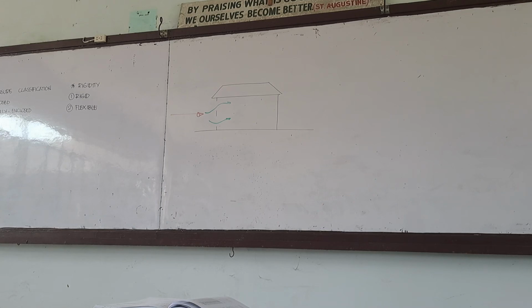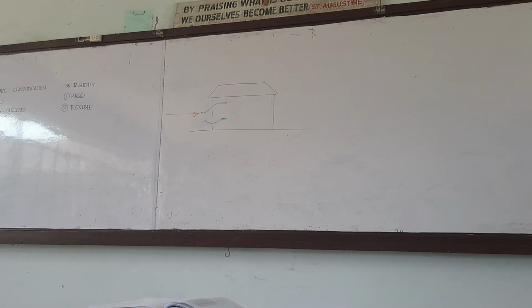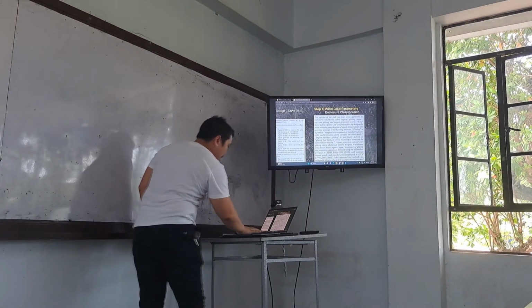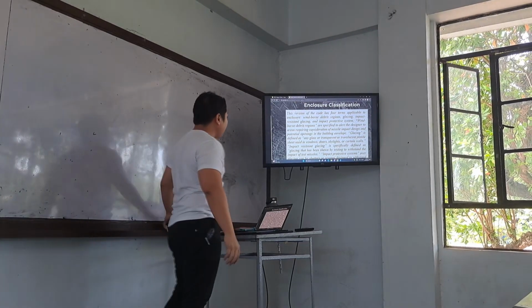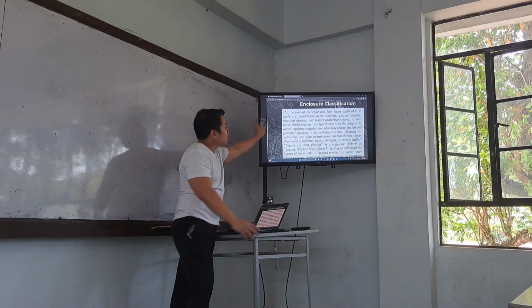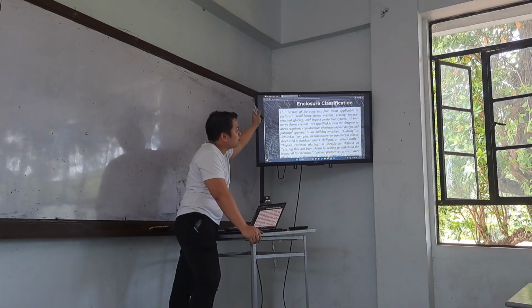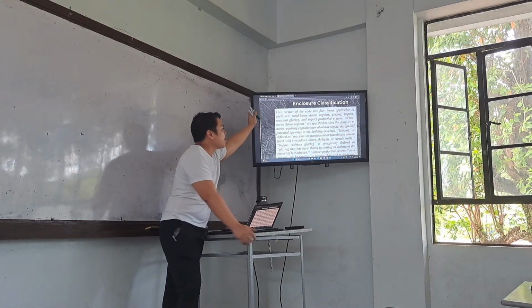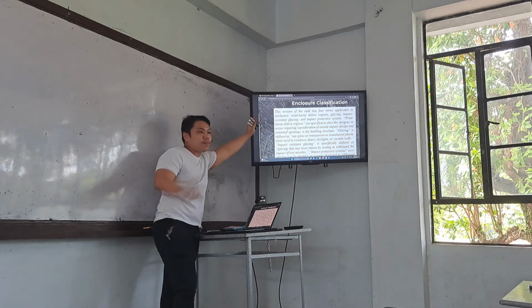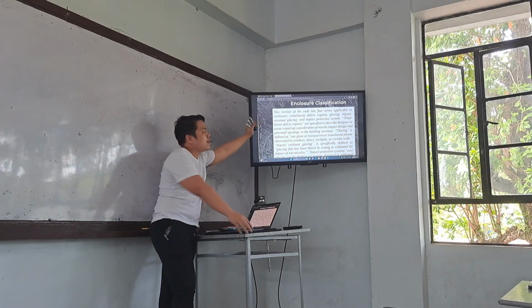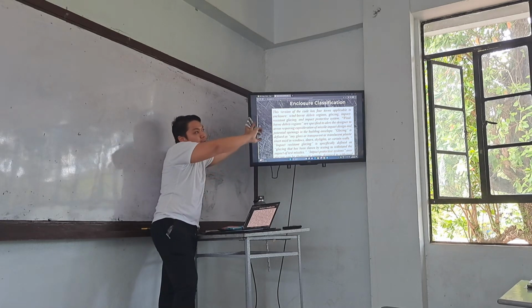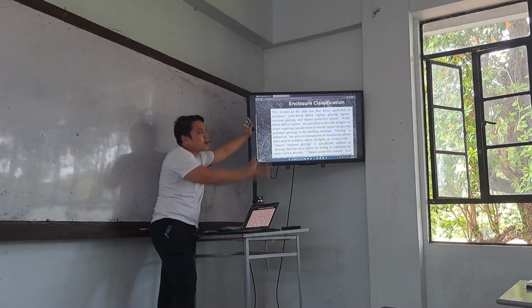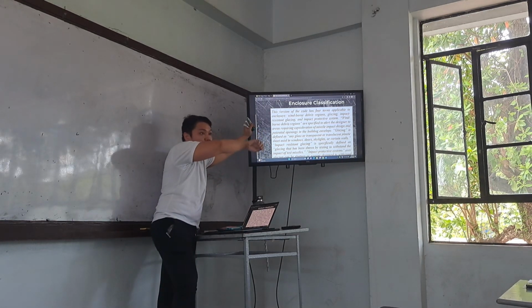So, we mentioned earlier, this version of the code has 4 terms applicable to enclosure: windborne debris regions, glazing, impact resistant glazing, and impact resistant. The consideration is that we will consider all debris around us during strong winds to have an impact on the glazing, which can break. Regardless of whether your window is tempered glass or annealed glass, it can become a source of our internal wind pressure.